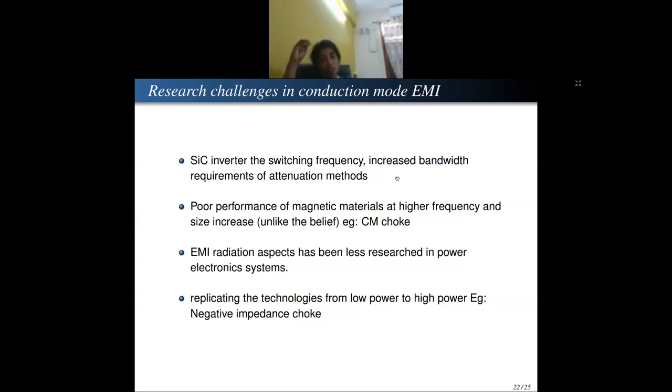That is the biggest problem of the electrical switch. You have to rise at a faster rate, and fall at a faster rate, so that it doesn't occupy most of the efficient time period. And the main concern until now to go to high switching frequency is losses. Since that was met, now SiC converters are more popularly being adopted, and technologies are being developed by many companies.